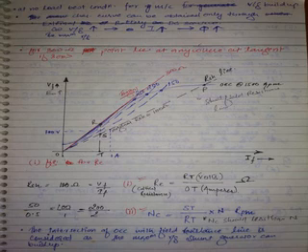Here, one important point: for a given machine, let us take this machine, 1500 RPM is the rated speed. And for this machine, in the manual, 900 RPM is given as the critical speed. Which means you have to operate this machine always at 900 or above 900. Below 900, you won't get any voltage. Only 6 to 8 volts, the residual voltage, will normally be there. That is the meaning of that.